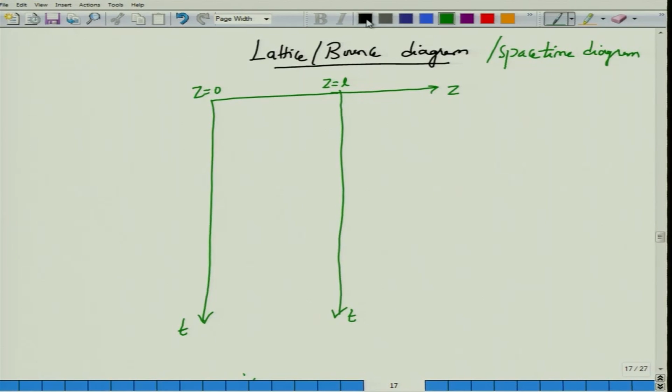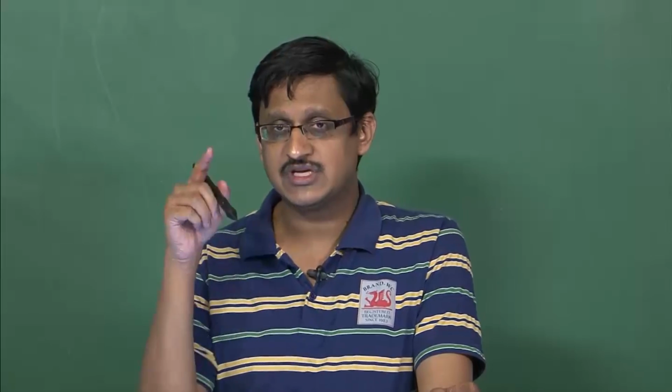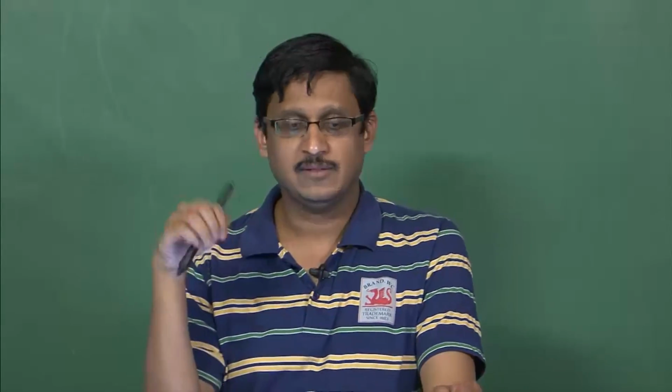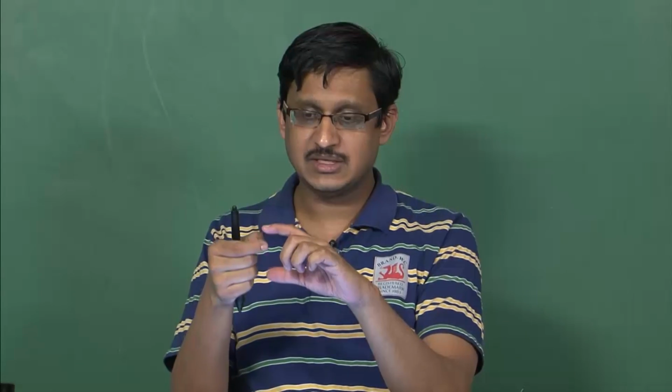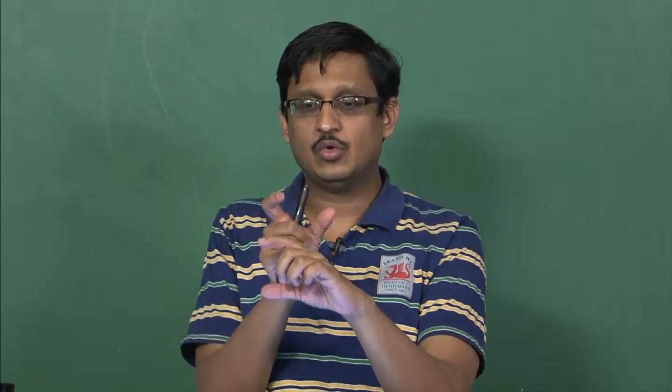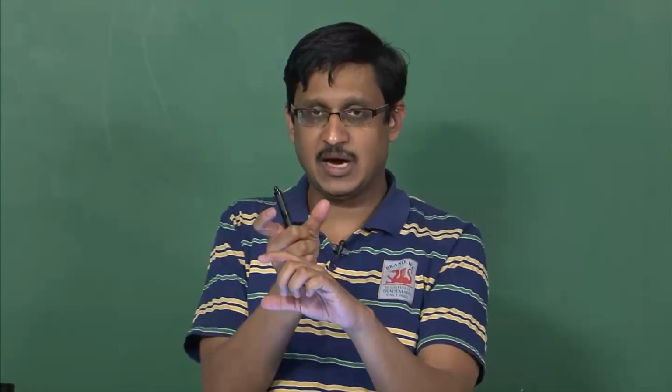The first step is to understand what is the initial voltage value that begins to charge the transmission line. Would it be equal to Vg? Well, unfortunately that would not be equal to Vg because Rg is present. If the generator resistance were equal to 0, then at t equal to 0 when you connect the source to the transmission line, the voltage initially launched would be equal to Vg. Because there is Rg and there is the characteristic resistance R0, the voltage gets divided between Rg and R0 in an appropriate voltage dividing ratio.